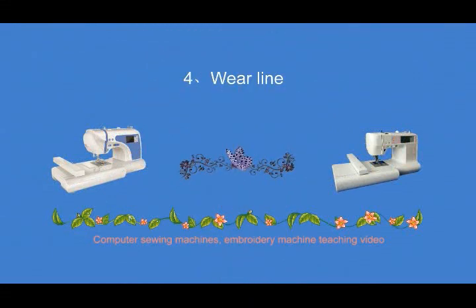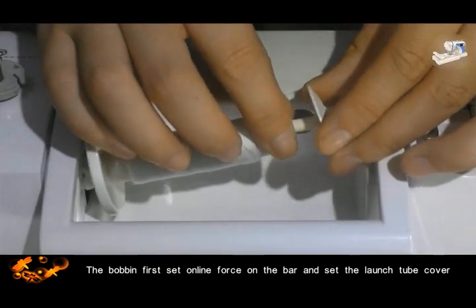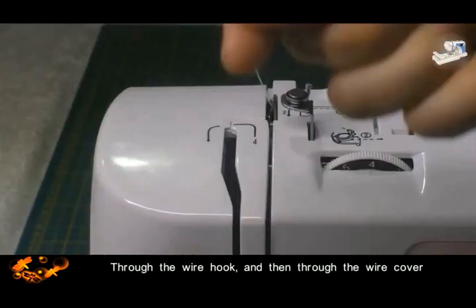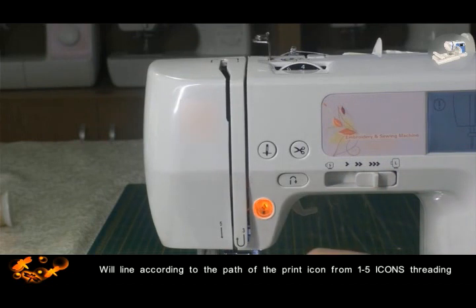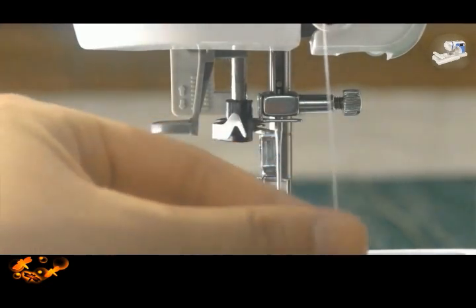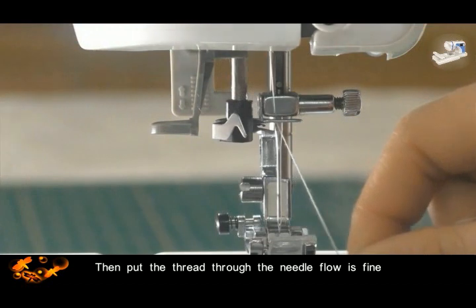4. Threading. First set the thread on the rod and set the thread cylinder cover. Follow the icon path with the thread, through the wire hook, and then through the wire cover. Thread according to the path of the printed icons from 1 to 5. Bypass the take-up. Then put the thread through. The needle flow is fine.